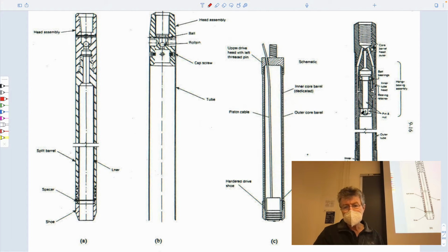And this central portion here that you see is the core barrel that's interior, that you can actually retrieve along the length of the sample. It doesn't look like it here, it looks like this thing's in the way, but you can retrieve the core barrel up through the sample without breaking all the drill string to come here.